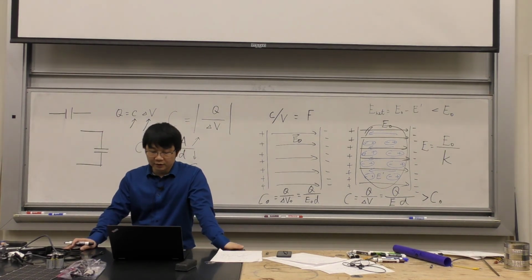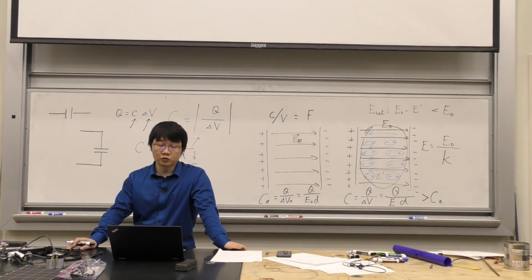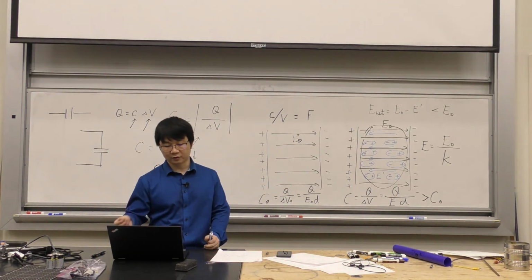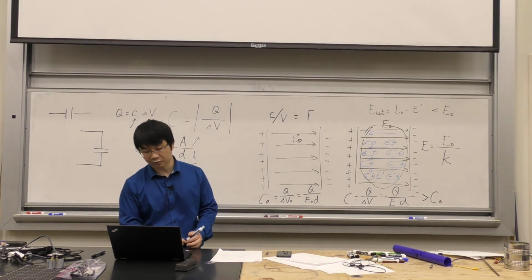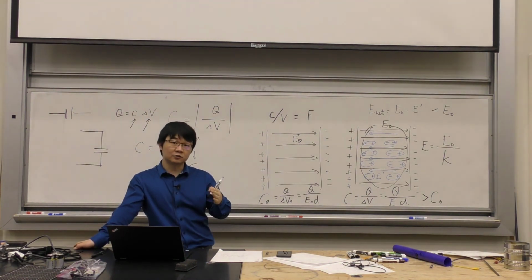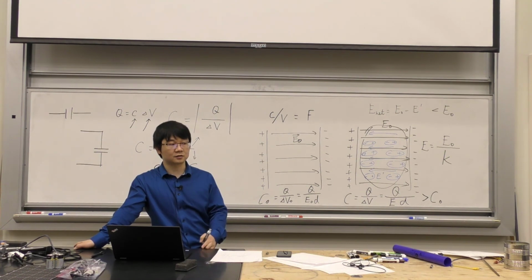So the insulator is going to become a conductor at a certain high voltage. That's called dielectric breakdown, right? So things around us are insulators at normal conditions. They may become conductors when the electric field in them is really high. That's called a dielectric breakdown. Okay. So for example, think about air. Right. Lightning is a real life example of dielectric breakdown. Okay. Why? Because air usually is a very good insulator. Right. You never conduct electricity using air. Right. I know that air doesn't conduct electricity.